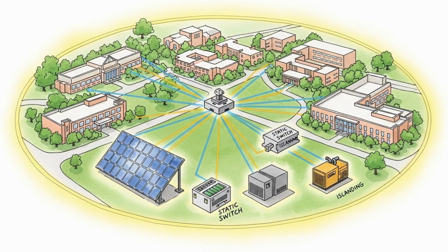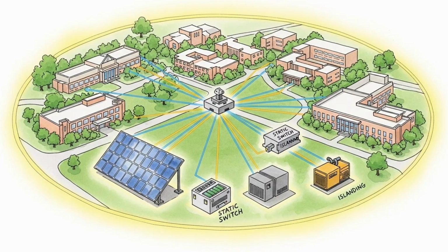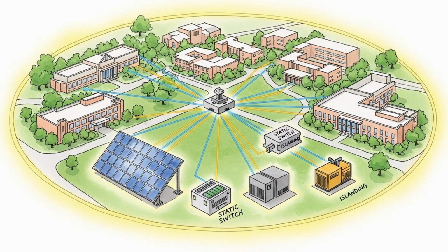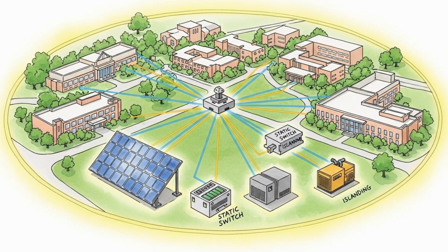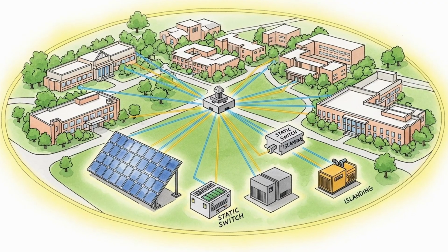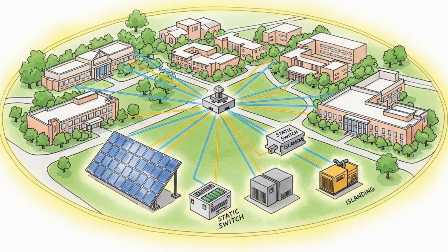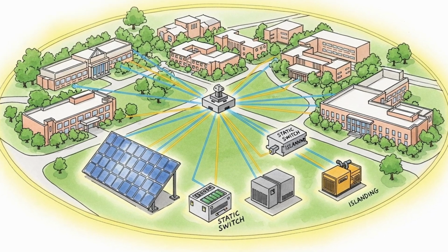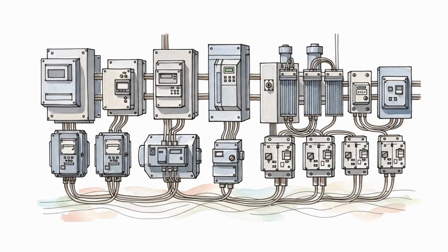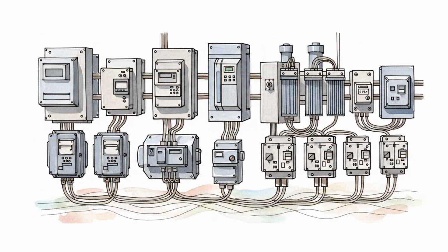on the ground. Electronic upsets occur when energetic particles strike sensitive nodes in memory or logic. Single event upsets flip bits. Single event transients create false pulses. In severe cases, single event latch-up draws excess current and forces a power reset.